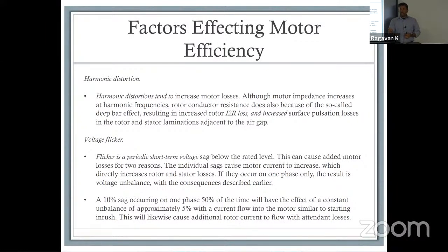If you don't do that, your controller algorithm is assuming a certain resistance. If you don't take into consideration the length of the wire, and let's say hypothetically it is relatively long, first and foremost you will have a variation in your resistance. Option two, if you have a wire that runs in a loop, in PCB design, that's one of those things you always talk about. You don't want to have big loops when you're designing a PCB because it creates what?